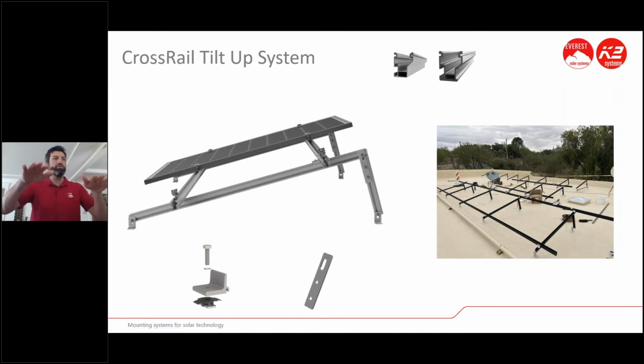So if you've got an uneven roof, you can install these legs, you can pre-assemble things, and you can put it in, and it's very easy to adjust on the fly. So you can install it, and even when the modules are in, you can lift parts and move things around to have some adjustability for different heights and whatnot.